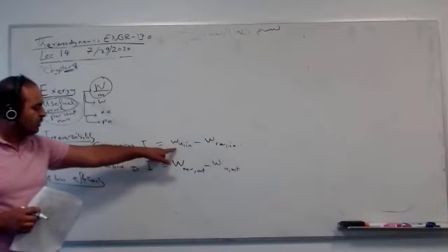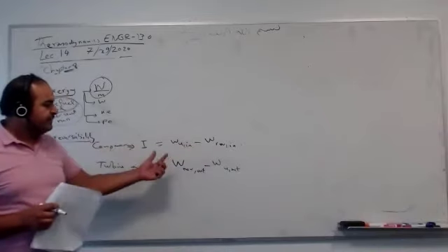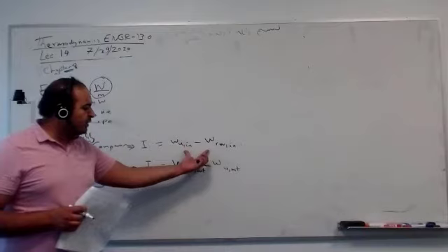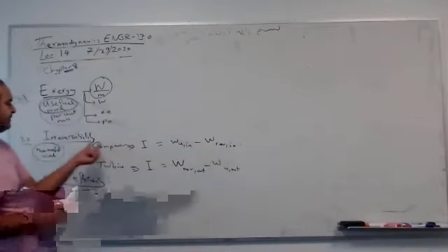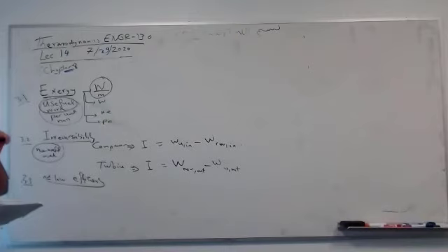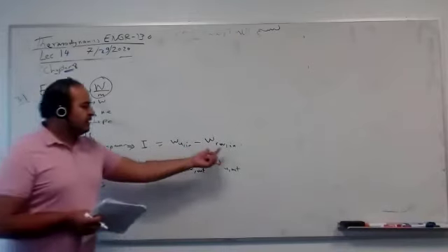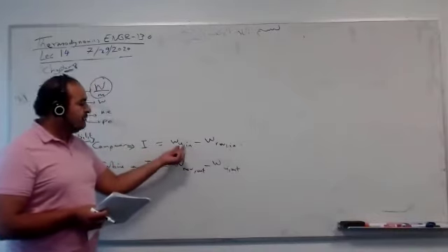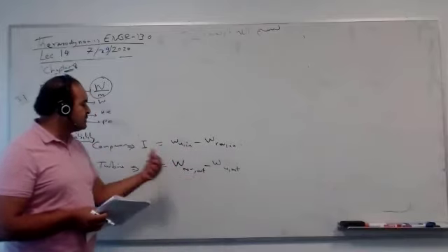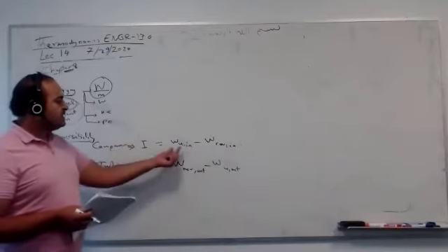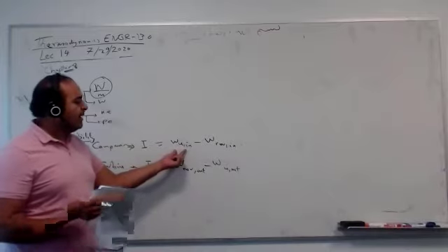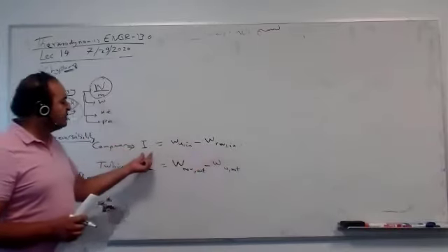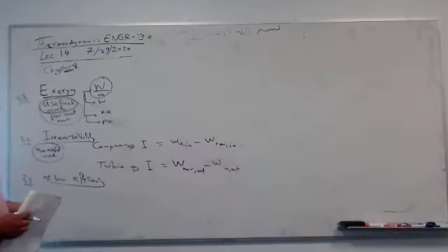In a compressor, I actually pay more than I'm supposed to pay. This extra non-useful work we call irreversibility. So if I compress flow in the pump from 1 to 10 atmospheres, I wish to pay this, but actually I pay more. It means I'm supposed to pay this to let the compressor compress this flow. So this actual work minus reversible work gives you how bad your system is in terms of extraction.